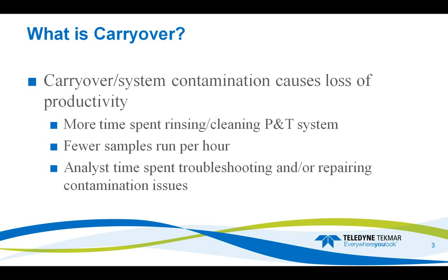Why is carryover bad? Well, it causes a loss of productivity and a loss of sensitivity. So when we have carryover, we have to spend more time cleaning, so maybe running rinse cycles in our purge and trap system. That leads to fewer samples being analyzed per hour, and if we're having trouble finding the source of that carryover or contamination, we spend a lot of time troubleshooting and trying to find that source, and that pulls us away from much more important things that we could be spending our time on.